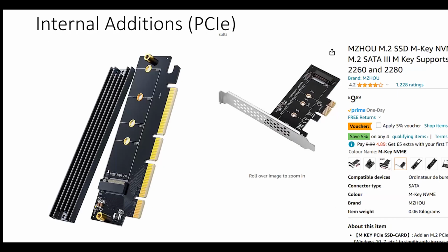Now you can buy these for a tenner, and I put two up specifically to let you see the difference. The one on the right, you can see the 22 pins with the clocks and the power supplies, and then you can see there's about 6 pins after that, after the keyway. That's a 1-lane NVMe drive.